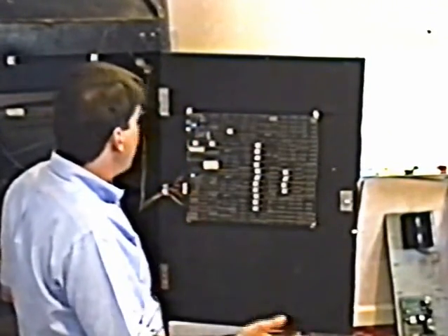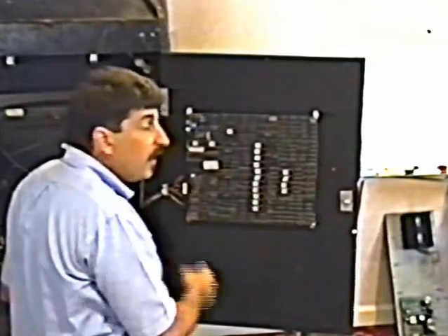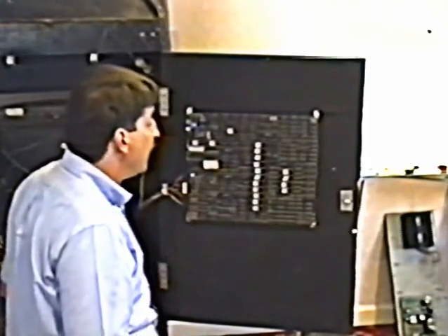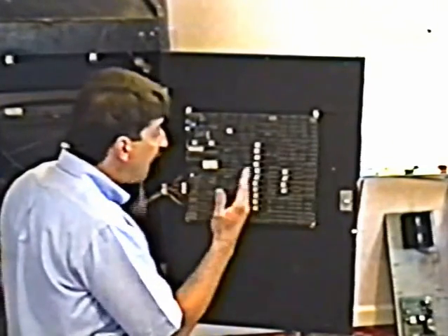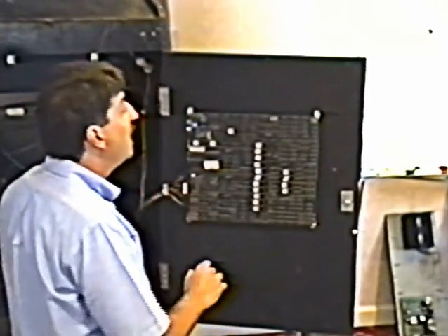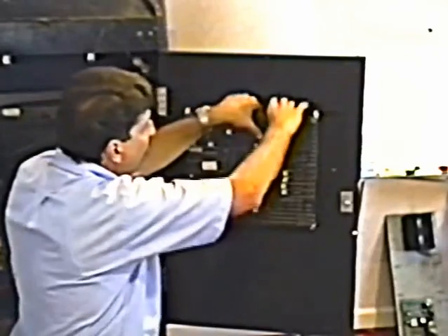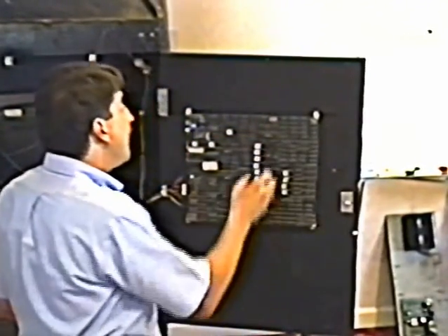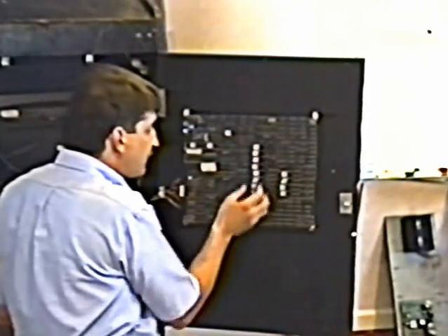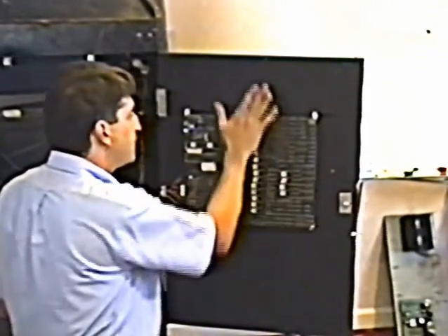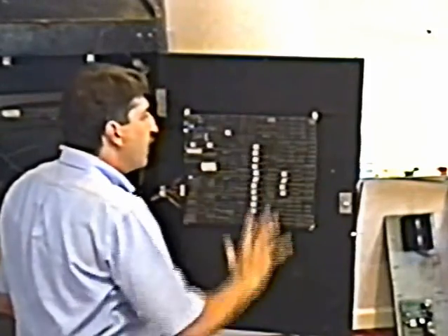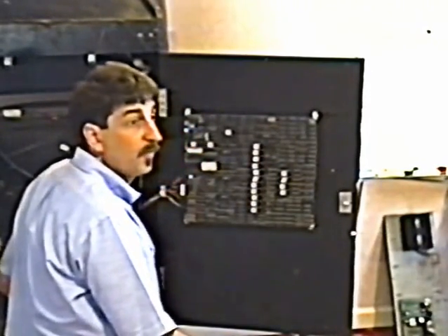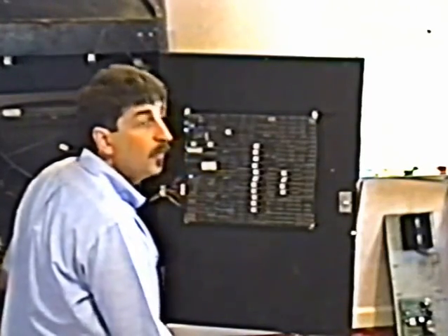So again, you get to the game, it's got this weird junk on the screen. First you check the power supply, because that's the most likely cause of that problem. But if the power's all okay, you definitely have a board failure. Don't give up. First thing, turn the power off, push on all the chips. Turn the power back on. Does it work? No. Carefully pull each chip out one at a time that's in a socket. Clean off the pins as necessary. Put them back in, fire it back up, see what you have. That really solves a lot of problems. I never send a board away without doing that first.